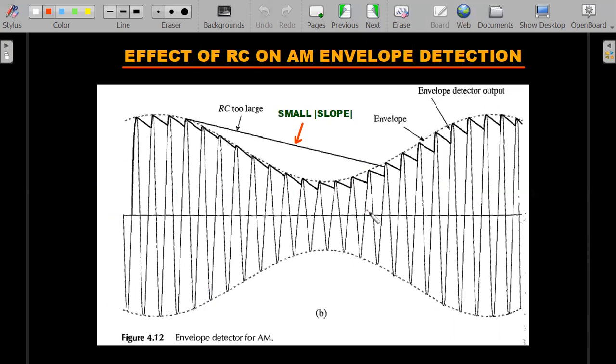So trying to enlarge that, we should understand that whenever it is going from peak to peak, whenever it reaches the peak, remember the diode in that rectifier is not functioning, that is, it is non-conducting, or it is in reverse bias. Then the decay will happen. So these small step lines you can see are the decaying of the RC circuit.